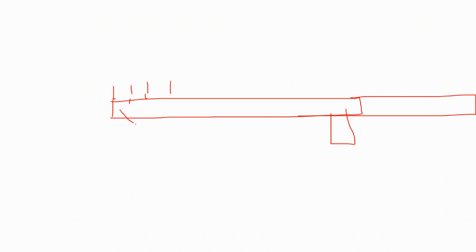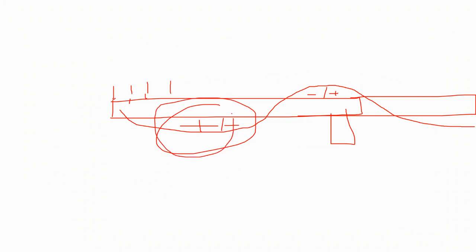So suppose this is my beam and this is the load which is acting. If there is a mid span support, now what can happen, the bending can happen like this and there can be a positive bending at the support also. So that's why we say this is positive or negative, you can say anything as per your convenience, and this is negative or positive opposite to what it is. So that's why we say there is some moment here also and there is some moment here also. So that's why we talk about tension reinforcement also and here compression reinforcement also.